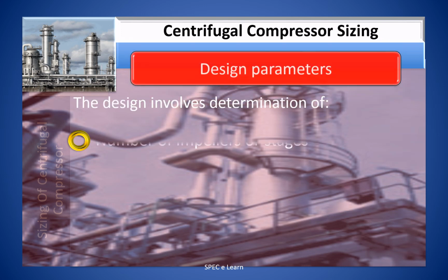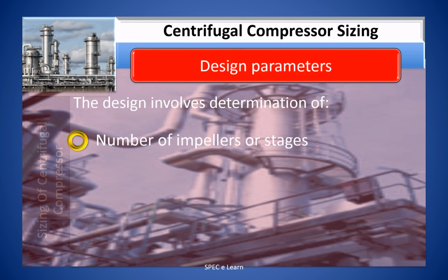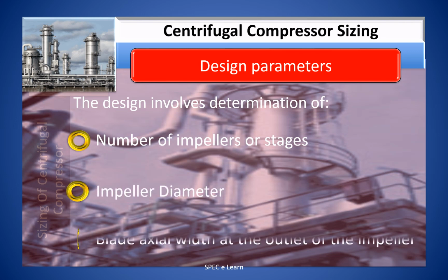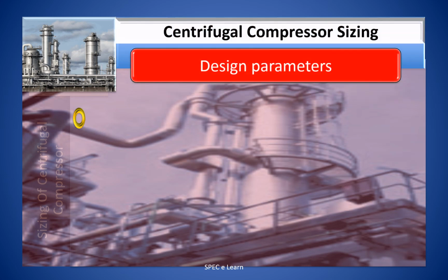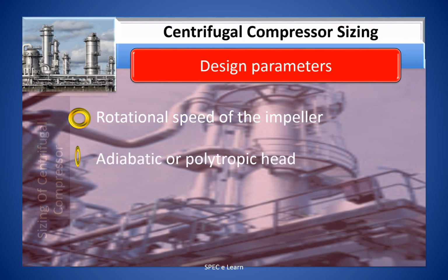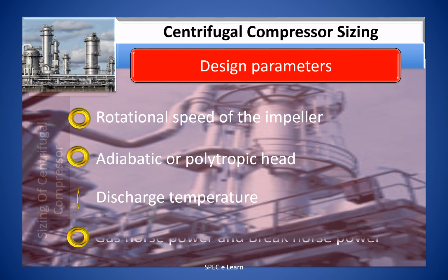The design involves determination of the number of impeller stages, impeller diameter, blade axial width at the outlet of the impeller, rotational speed of the impeller, adiabatic or polytropic head, discharge temperature, gas horsepower and brake horsepower.